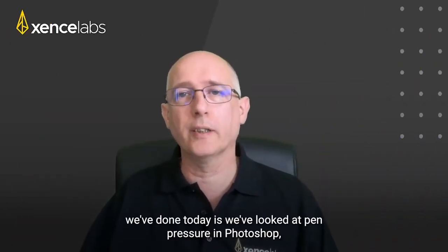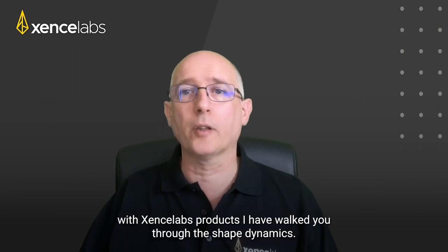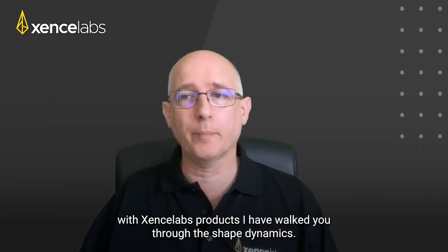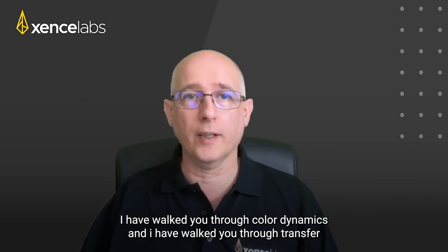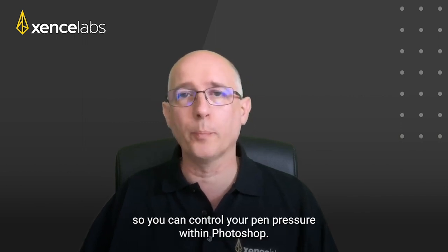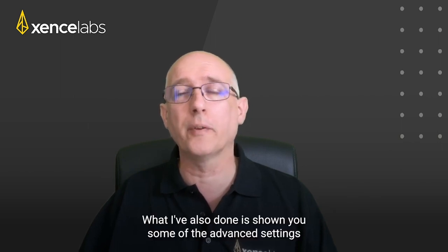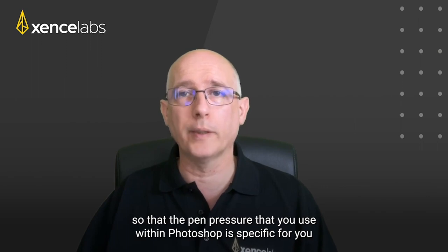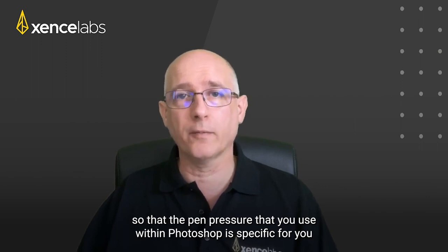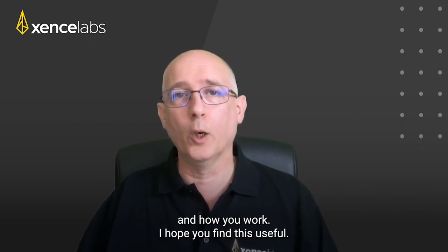So what we've done today is we've looked at pen pressure in Photoshop with Xencelabs products. I've walked you through the shape dynamics, I've walked you through color dynamics, and I've walked you through transfer so you can control your pen pressure within Photoshop. What I've also done is shown you some of the advanced settings within the Xencelabs panel for the driver that allows you just to fine tune so that the pen pressure that you use within Photoshop is specific for you and how you work. Hope you find this useful.